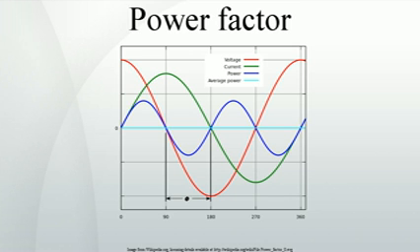For example, SMPS with passive PFC can achieve power factor of about 0.7-0.75, SMPS with active PFC, up to 0.99 power factor, while a SMPS without any power factor correction has a power factor of only about 0.55-0.65. Due to their very wide input voltage range, many power supplies with active PFC can automatically adjust to operate on AC power from about 100 V, Japan, to 230 V, Europe. That feature is particularly welcome in power supplies for laptops.